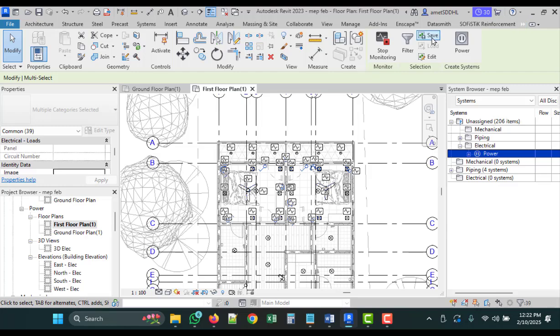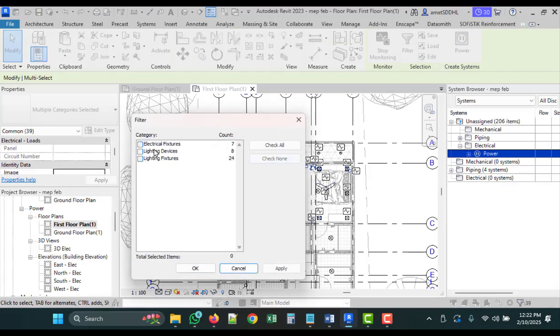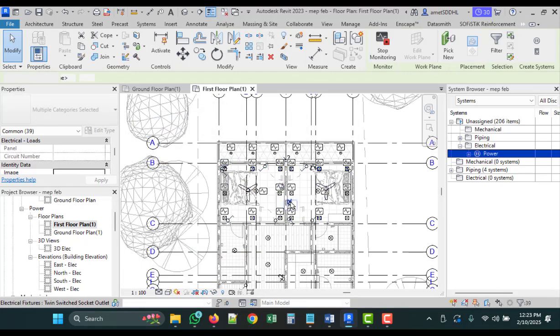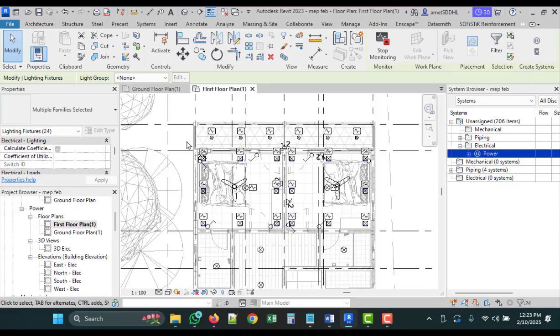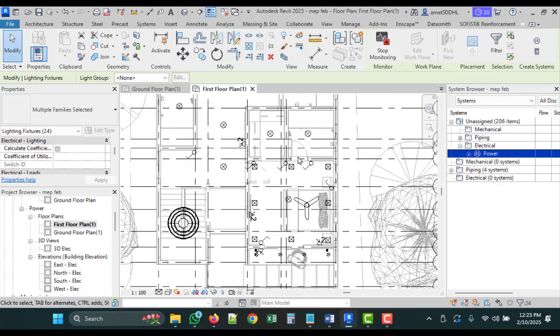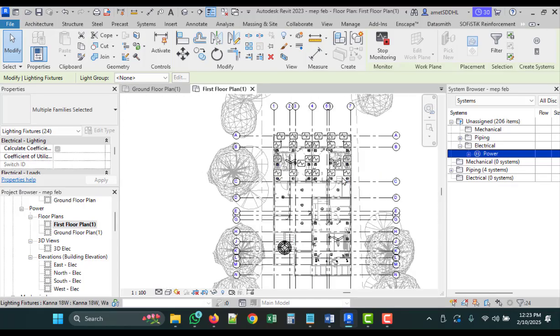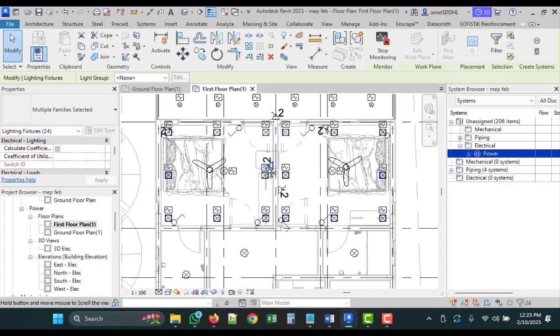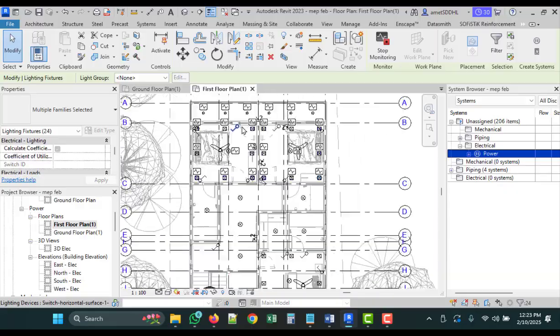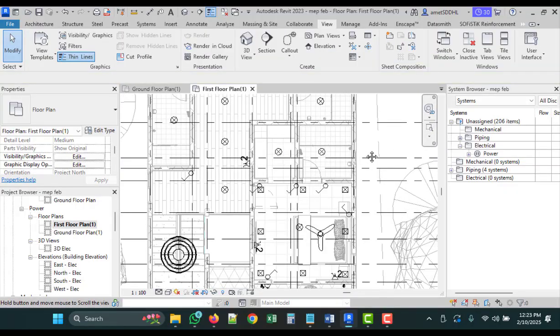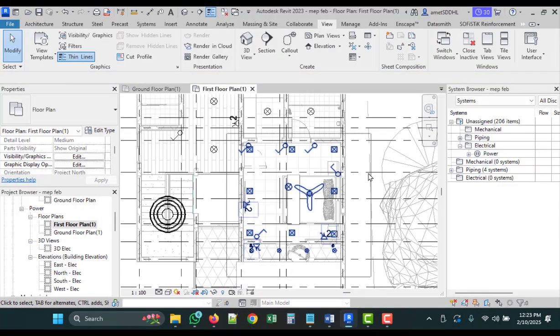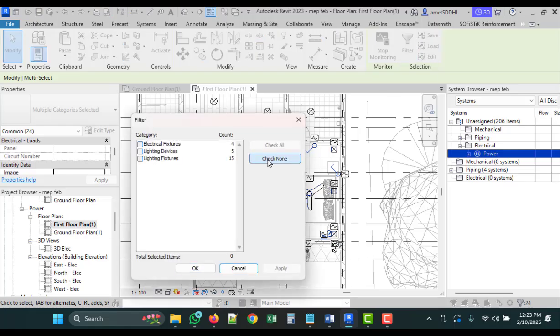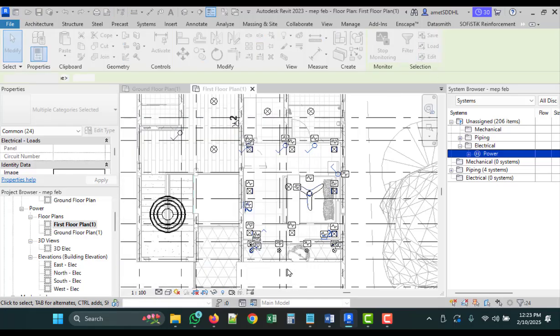And then I'll filter out the lighting fixtures. So they all have the power, so I'll do that. So probably the issue is from this side, but I'll connect this, then I'll add the rest later. So with all this selected, or let me quickly see, let me check which light might be the problem. So I'll select the lights here, filter, lighting fixtures.